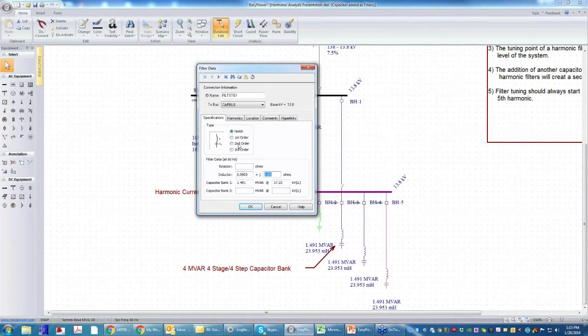The other filter that's common is the high-pass filter. Really, the only difference here is you would model ohms for the resistor. So remember, there's a resistance in parallel with the reactor, and there is a value of R there. So you might ask, well, how do you pick R? How do you pick the resistance of the high-pass filter?